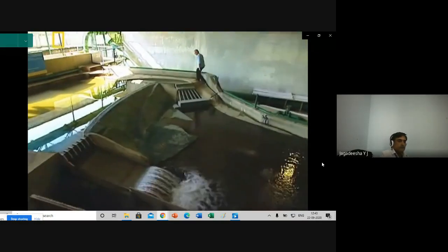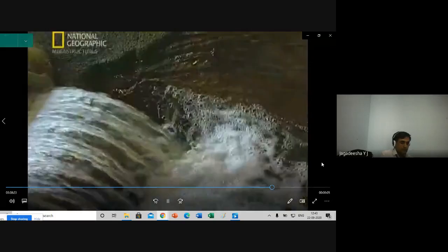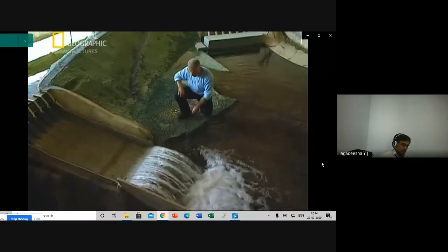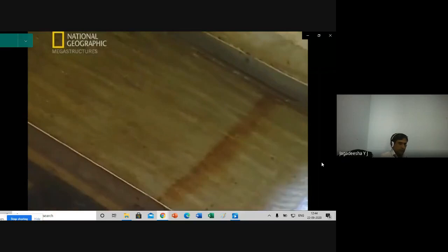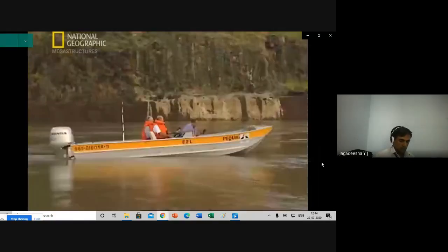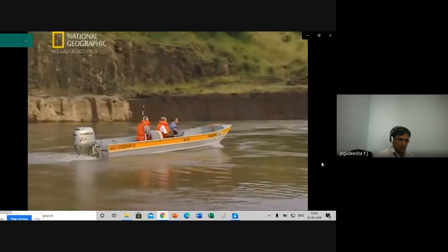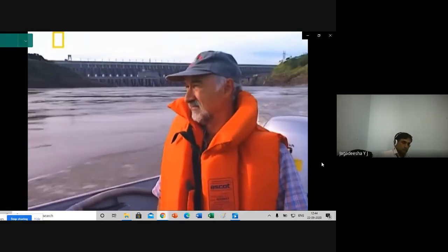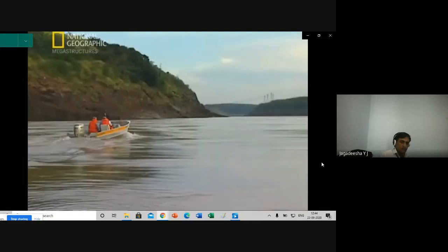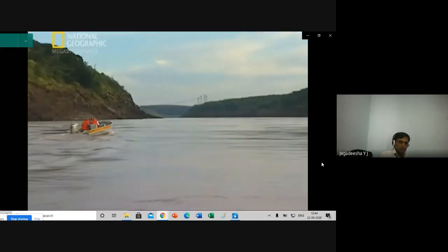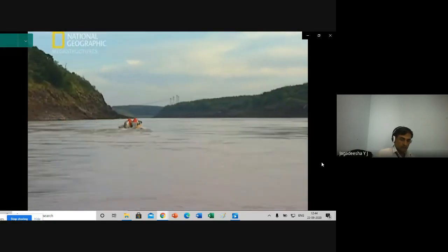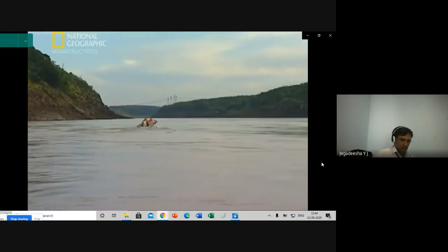Engineers relied on scale models to get the angle of the ski jump just right. If it's wrong, the water will turn back on itself and could seriously erode the riverbank. And if the process continued over years, it could eat away at the foundations of the dam. Itaipu's engineers have calculated that there will be some erosion, but not enough to do any serious damage. All they can do for now is keep checking the riverbank and hope. If they've got it wrong, the structure of the dam itself could be in peril.